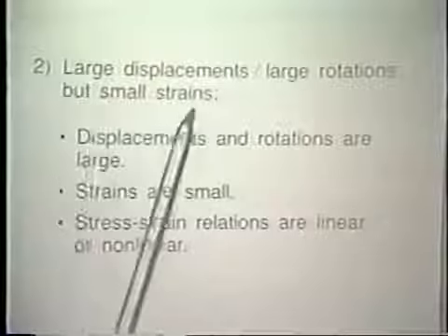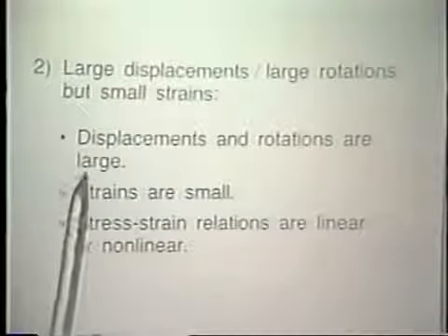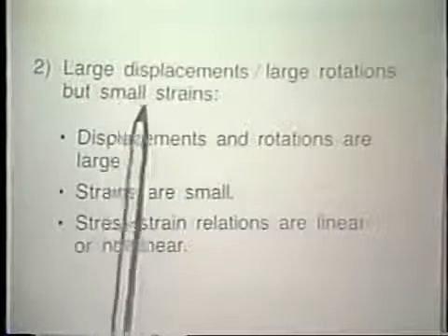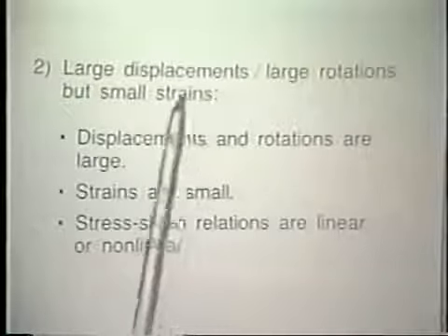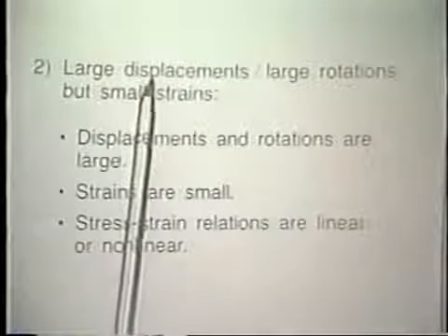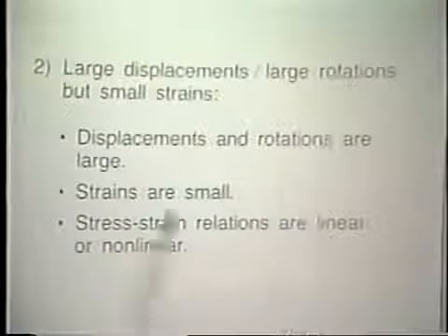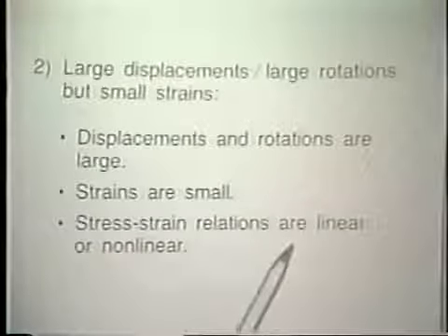The next category of problems is the one of large displacements, large rotations, but small strains. Here, in other words, we still keep the assumption of small strain, but we allow large displacements and large rotations. The stress-strain relations can be linear or nonlinear.